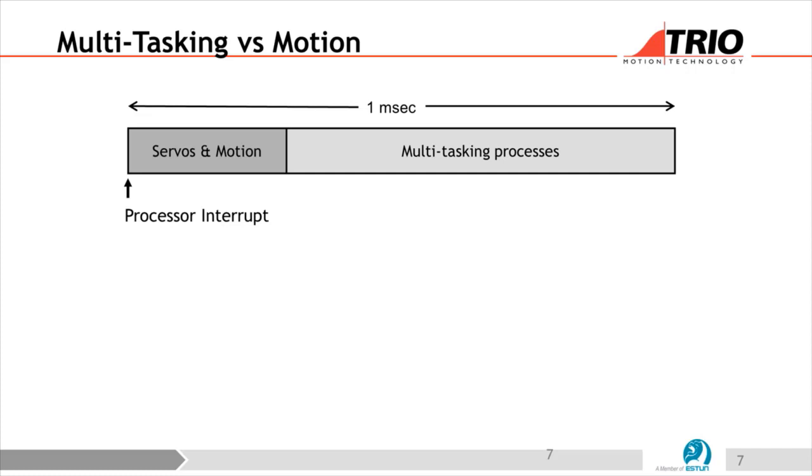And you'd be surprised, even if there's a 1 millisecond break in a move, you would see it. You might even hear it in the servo motor. There'd be a little tiny dink sound or knocking sound as there's a slight disjoint in the motion being processed. So it's very important that that is processed every millisecond without fail. And that's really what our system is designed to do.